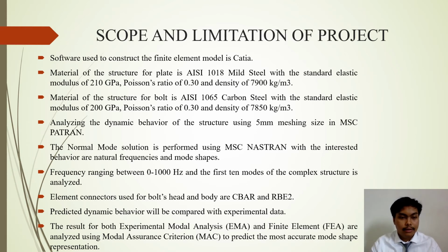Then, the normal mode solution is performed using MSC Nastran, with the behaviors of interest being natural frequencies and mode shapes. Frequency ranging between 0 to 1000 Hz and the first 10 modes of the complex structure is analyzed. Element connectors used for bolt's head and body are C-bar and RBE2.